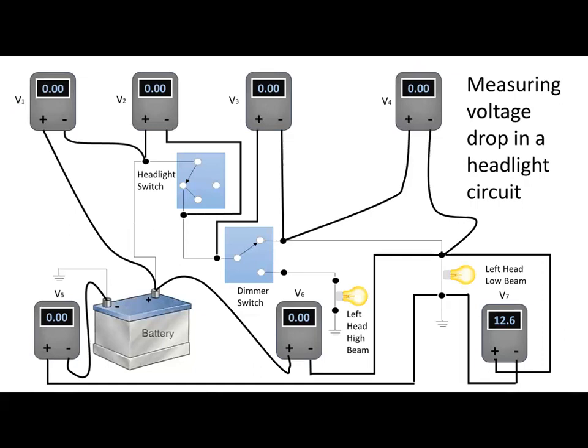In most parts of the headlight circuit, except the headlight itself, voltage drop over 0.2 volts is excessive. Excessive voltage drop through a connector is the most common fault in the light system. Pay attention to connectors that are exposed to harsh environments, such as fog light or headlight connectors that are repeatedly subjected to water or road chemicals.